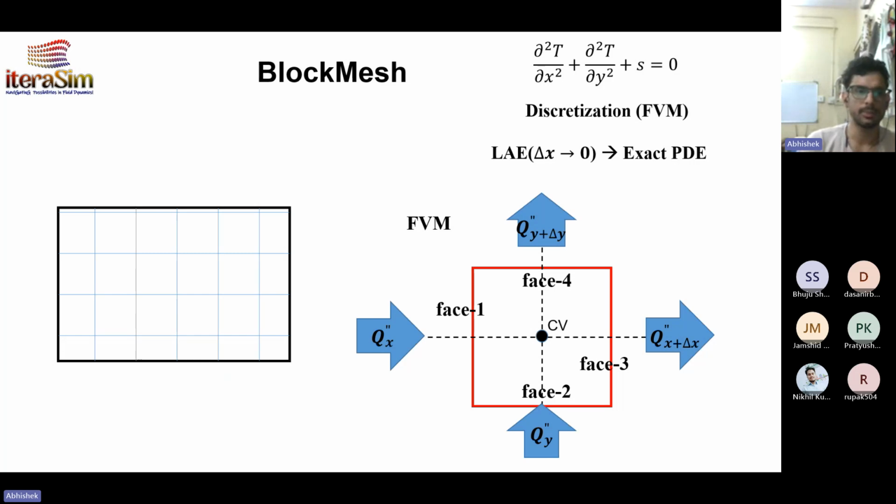This is typically a structured Cartesian mesh in which, using the iterative solver, we first solve for the bottommost row, or in the x direction, and then we move slowly in the y direction. So we move row by row. So we don't need numbering of the cell centers.